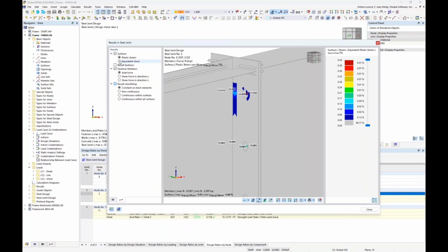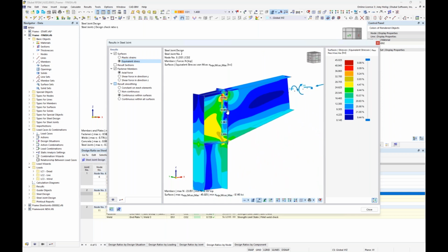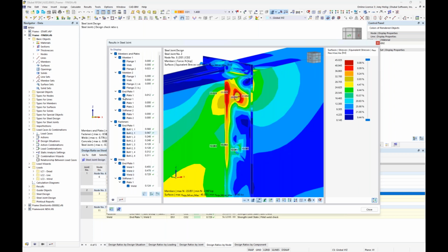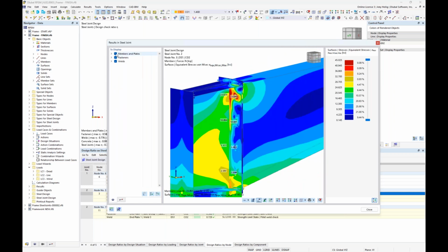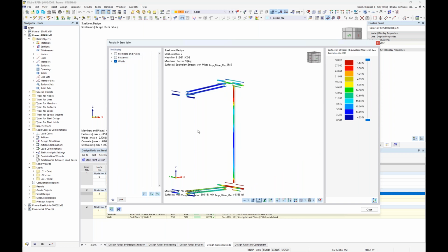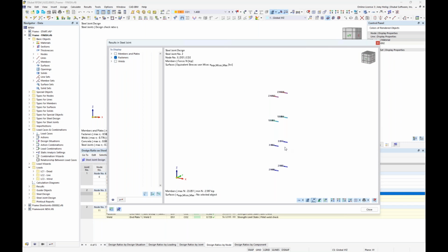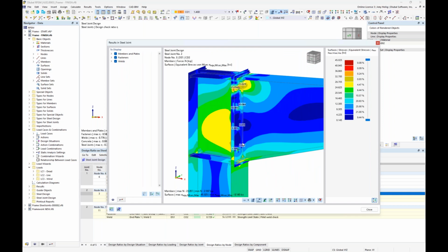Now, alternatively, we can toggle this to the stresses instead. And this might look a little bit more interesting, that we can actually view the stresses for all of our components here graphically. And of course, where we saw those higher strains, we're also going to see those higher stresses given. So going back to this initial tab, if I go ahead and collapse these different display options here, I have the ability to actually turn off completely my members and plates and maybe my fasteners. And now I can view the stresses just on the weld elements themselves. Or if I'd like to turn on the bolts, I can go ahead and activate here the fasteners, and we see the tension forces in kips given to us graphically. And finally, going back to the display of all of these options, we go back to the stresses shown for all components.